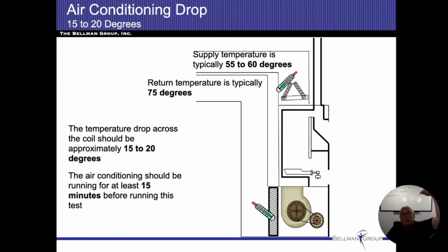But I do take the temperature above the plenum up there, and I'll usually either remove the humidifier and get access to that area, or look for gaps in the ductwork itself, and if I can't, I'll find the closest radiator. For those of you that decide you want to work with a thermal imaging camera, they're actually pretty cool. You just walk right by the registers, and you can get a reading of whatever the temperature is that's coming out of there. What you don't want to do with those things is shine it on the ductwork.